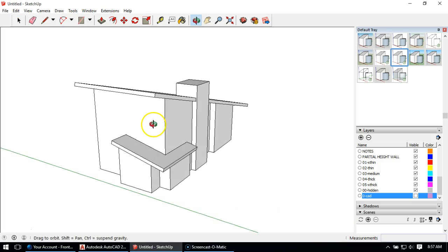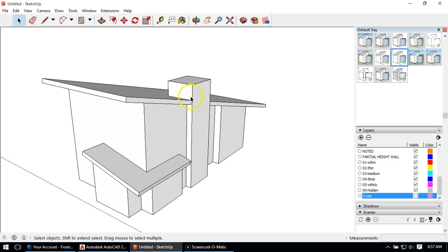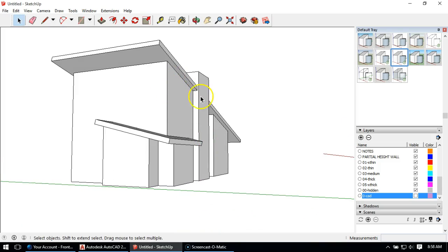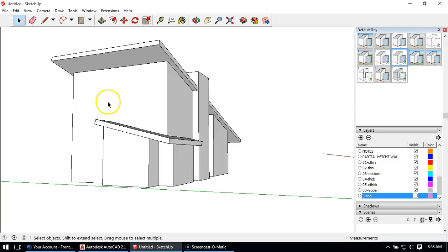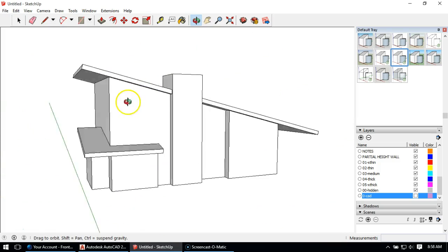The other thing I sort of realized when I did this, which you may have done too, when I set this roof the first time, I think I must have set it off of the front face here. And I set the 1'2" off, but the reality is it's off of this face here. So my roof wasn't quite set right, and it wasn't even quite the right width. So when I was off screen finishing this, at some point I saw that, and I had to fix that based on my model. With my CAD model on, I saw how it was working. So it is a little tricky, especially to fix this corner here, but it's just basic modeling stuff once you run intersect with model. So I've got the roof done, and I've got the basic shape of my building done.